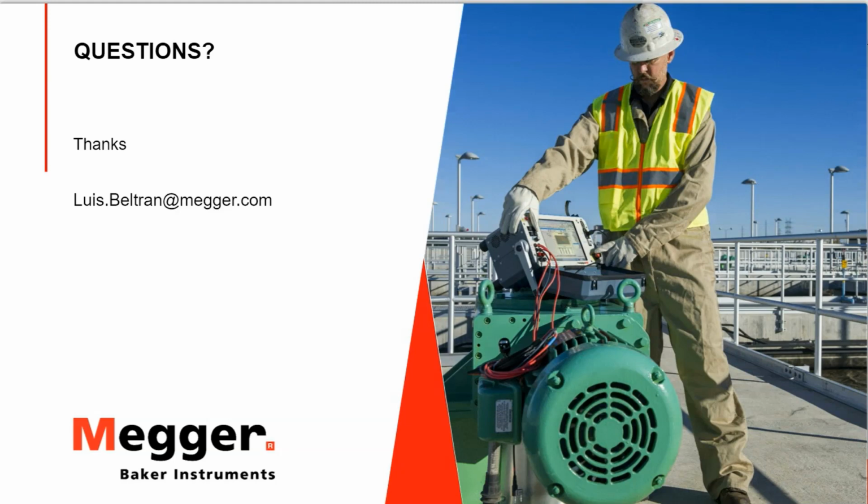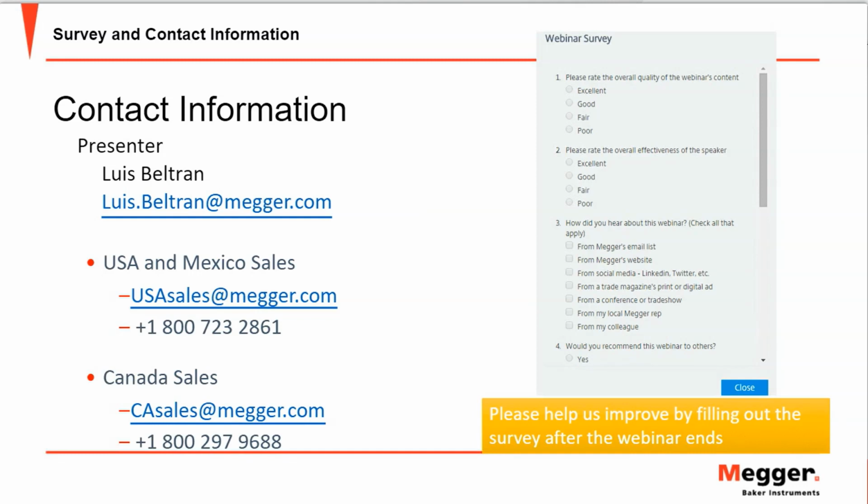Hi, thanks, Mike. That's a good question. Well, basically every time you do maintenance on the asset, when you build the asset, you do the surge test to verify that there is no turn-to-turn failure. The surge test is not a destructive test. Therefore, you can basically run it on the asset anytime you have a maintenance cycle, and it will not lower the life of your asset. You will actually determine whether your asset is in good condition or not.